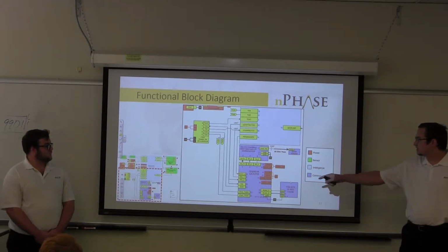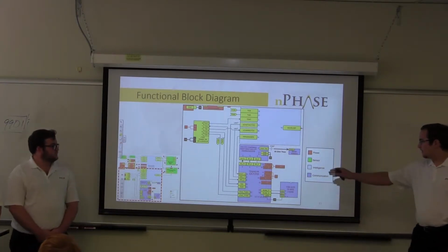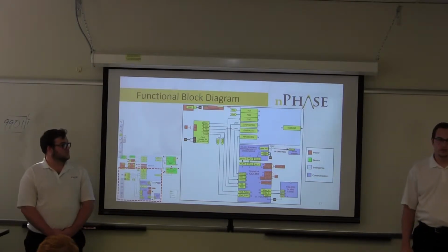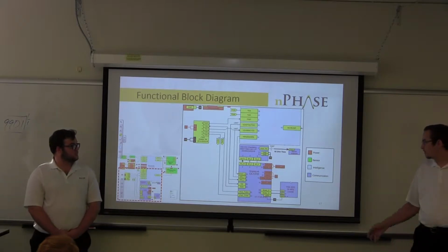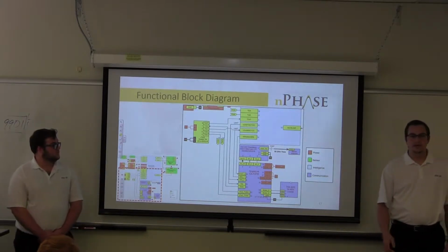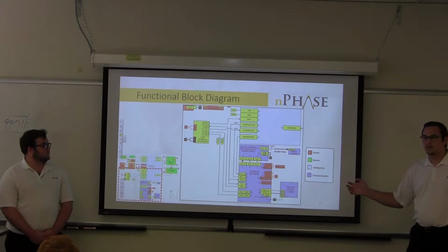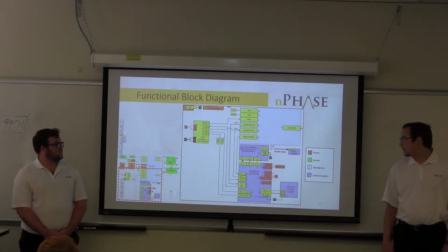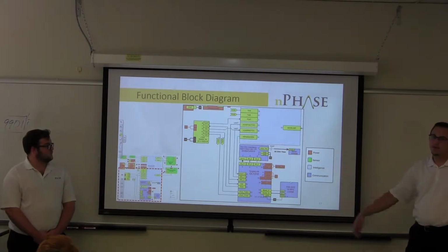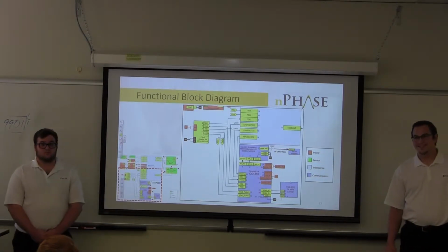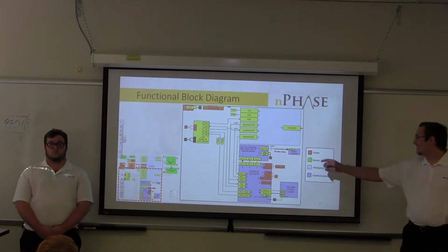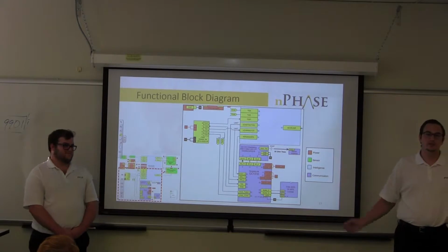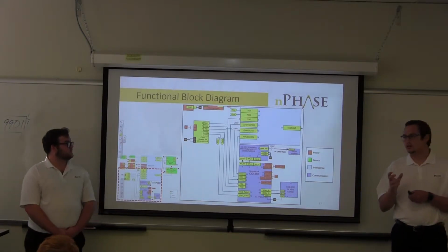And then down here in the CC1310, it goes to a balun, which is used for impedance matching. Instead, we could apply circuitry to go to the antenna using a bunch of capacitors or inductors, but this does the exact same thing while conserving space. And then we have it go to a 100 picofarad capacitor, and from that 100 picofarad capacitor is a 50 ohm trace to our sticker antenna, which will be connected to our enclosure.